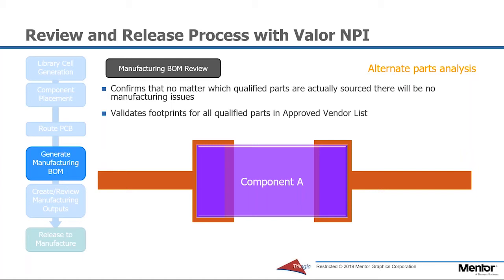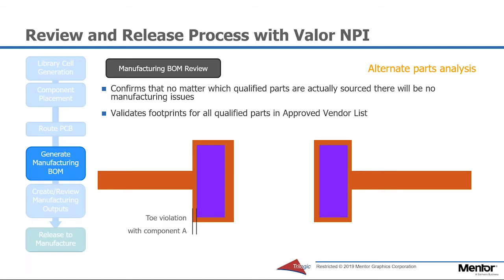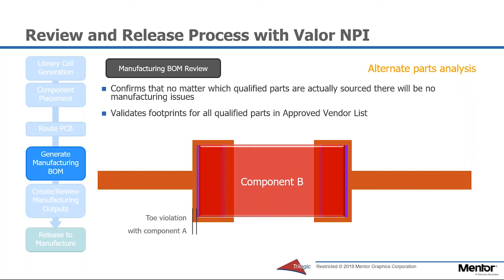Valor simulates the mounting of component A on the board. In this case, a toe violation is identified. Component B is validated, and for component C, there is a pin to pad side violation.